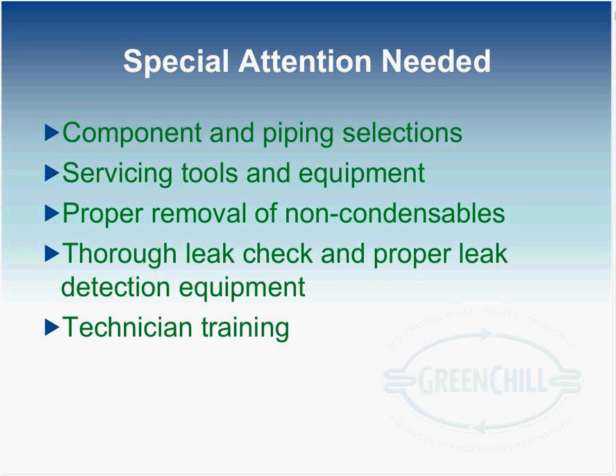Another important piece of equipment to be noted for use with CO2 would be leak detection equipment that is designed for use with CO2. Next, just in a second, on non-condensables. Non-condensables can hinder the performance of any refrigeration system, but it's extremely important to remove all non-condensables from a CO2 system, as they will affect the performance as well as the operation of the CO2 system.